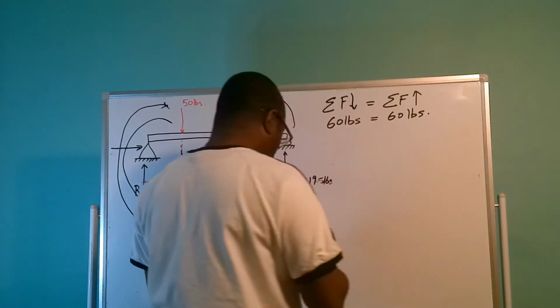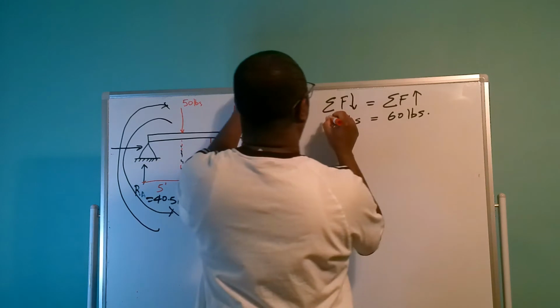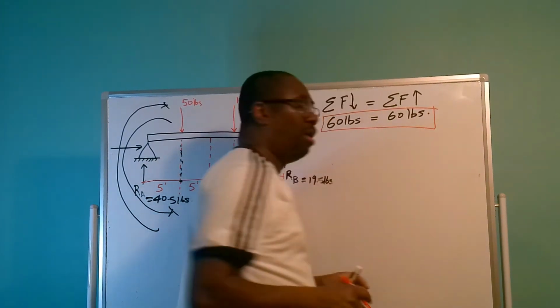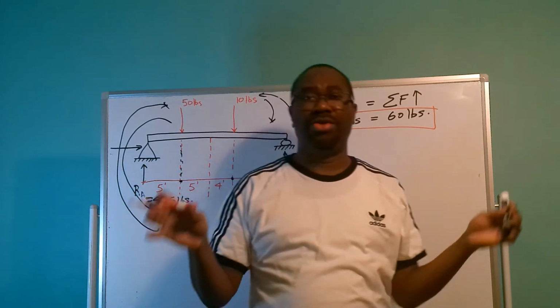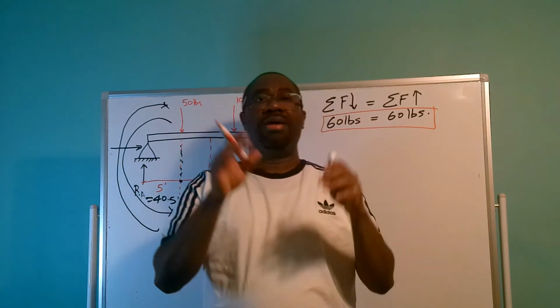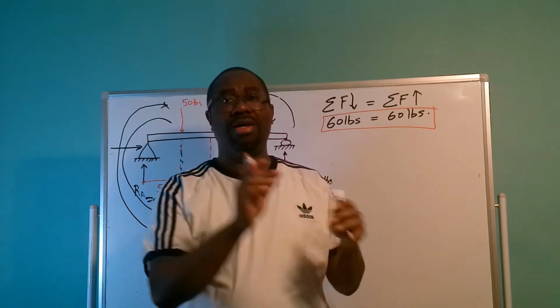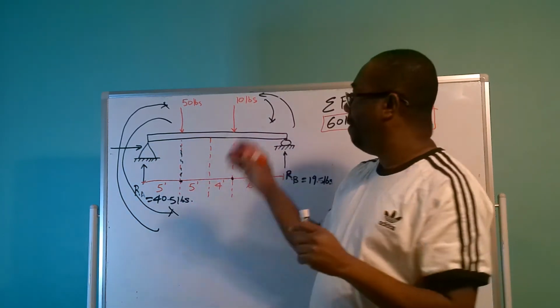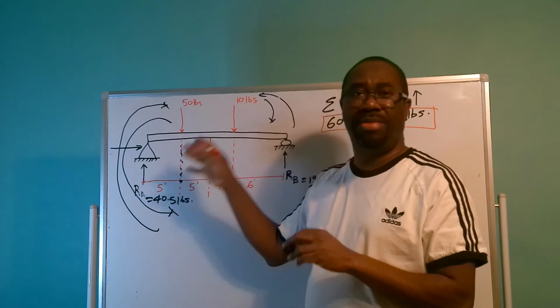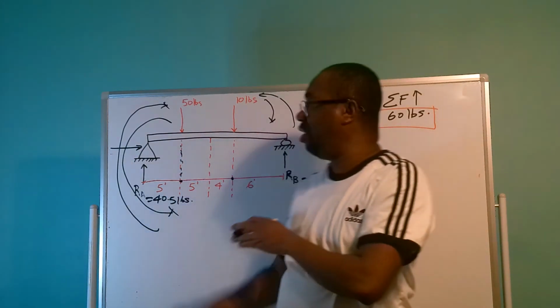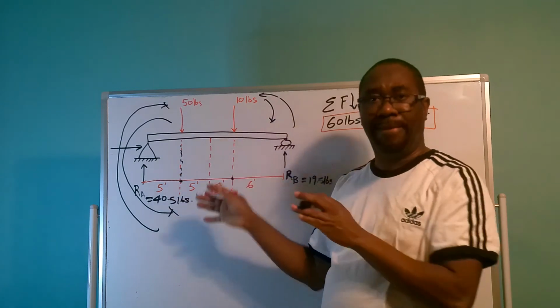So now that I have done that, I can move to calculate my shear force and my bending moments, to get the maximum bending moment that is going to be needed to plug into the formula to calculate the reinforcement for this beam.